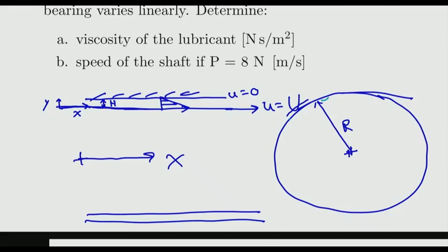So you could assume x, y, and then tau is equal to mu du dy, and that's what we discussed. Because we're considering that it's essentially a flat surface, consider this local coordinate y, and just use the previous expression we discussed in class. Then you could figure out u as a function of y for this very simple linear problem. Okay? Yeah? Is h 1 millimeter? Is it 1 millimeter total?